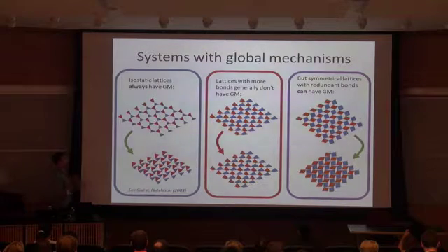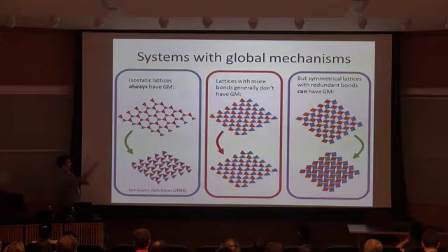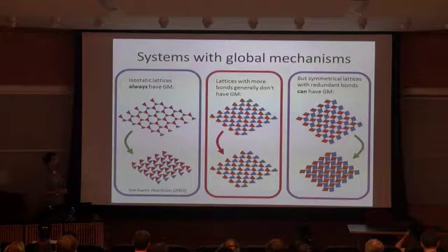If you have a lattice that's not a Maxwell lattice, that's not true anymore. You can certainly have stable mechanical frames if you put in enough bonds. But even in such a lattice with extra bonds relative to a Maxwell lattice, if you look at the panel all the way on the right, you can have redundant bonds. So on the right, each tile is a parallelogram, and this means that there's a way still to uniformly rotate it despite the fact that it has more bonds.